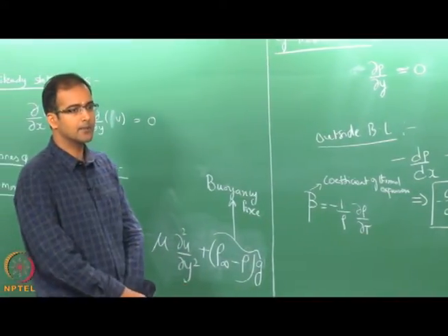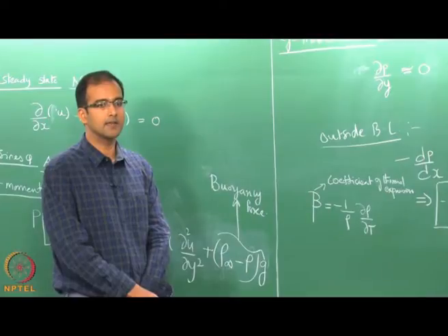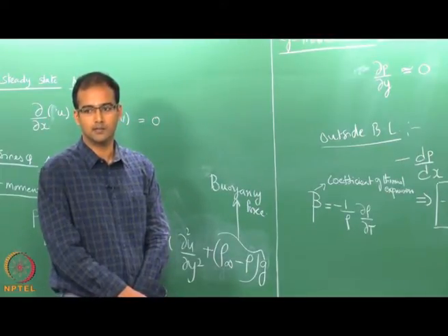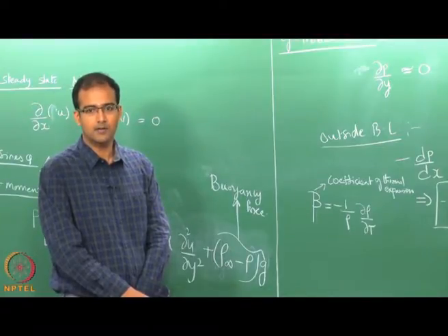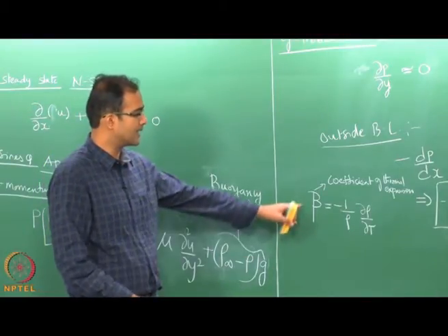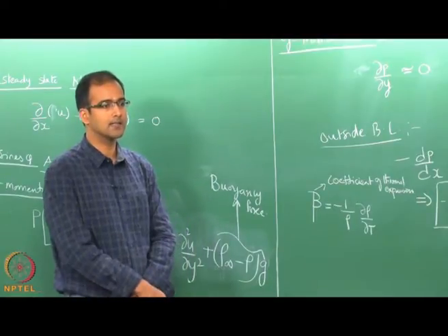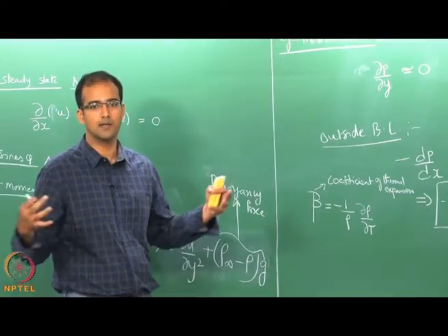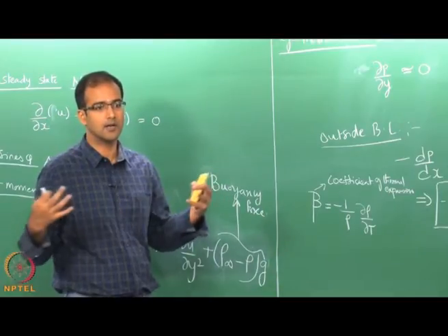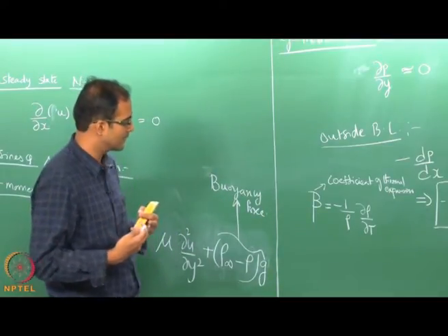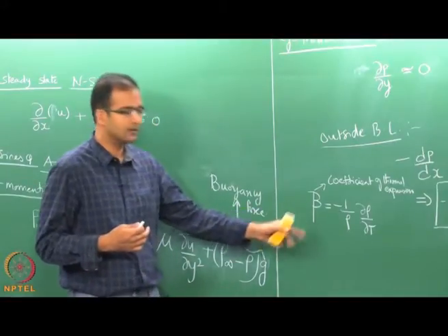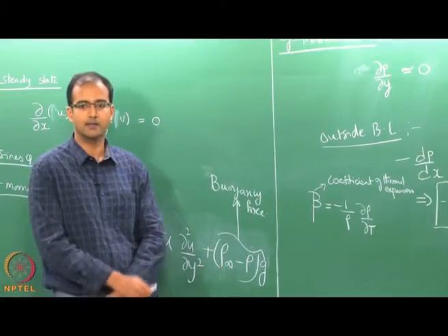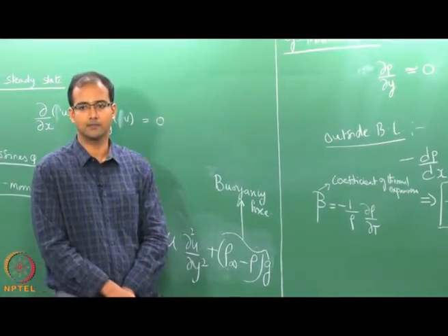What it simply measures is the variation of density of a particular fluid with respect to temperature. So, if this coefficient is high, that means you have a potential that this fluid can expand or contract very quickly, very strongly as a function of temperature. So, the higher value of beta indicates that the potential for this density difference can be higher.